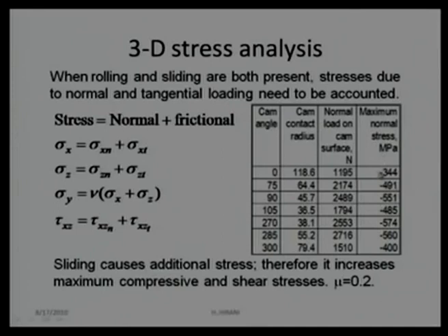These cam followers are generally supplied with a grease having a low NLGI grade, which can be easily pumped. If it is easily pumped using NLGI grade 1 and 2, it will not be very effective at keeping the lubricant layer at that interface. So it should be mixed with molybdenum disulfide or a solid lubricant to get good results.